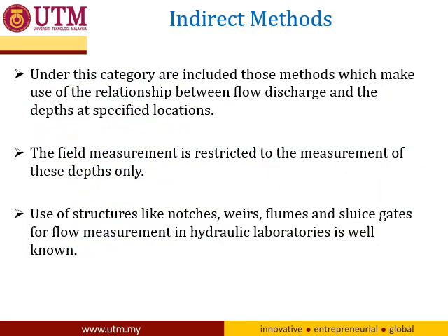Okay, next we have this indirect method. What is this? Under this category are included those methods which make use of the relationship between flow, discharge, and depths at specified locations. The field measurement is restricted to the measurement of these depths only. Again, the value recorded is just the depth.